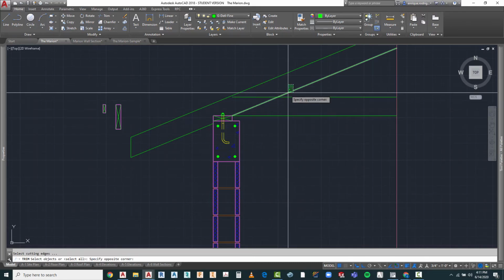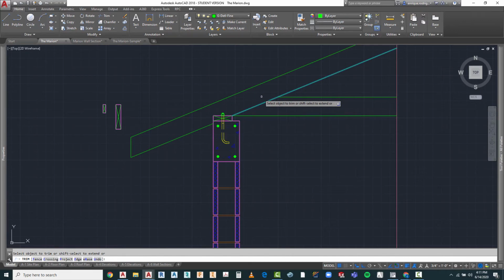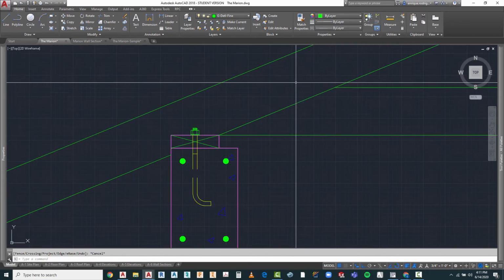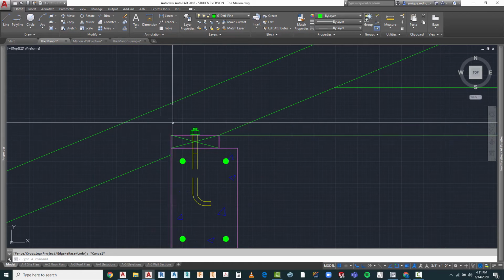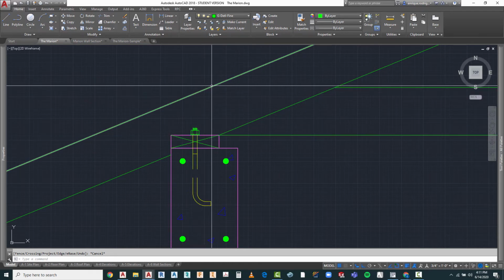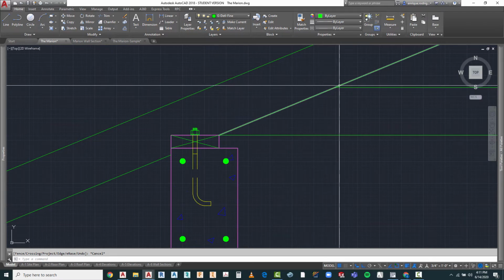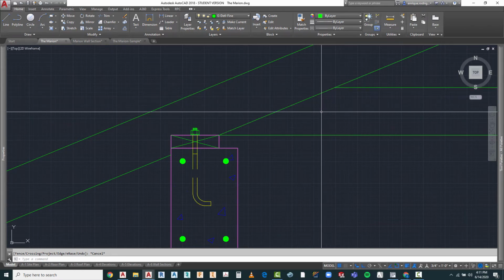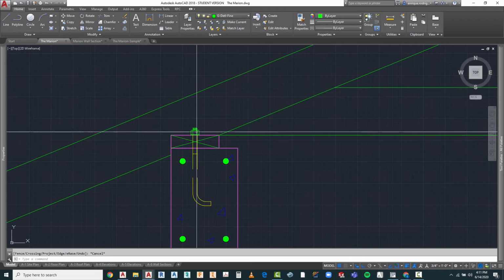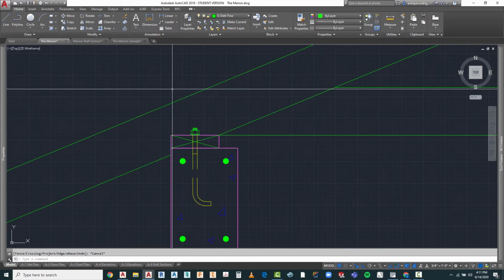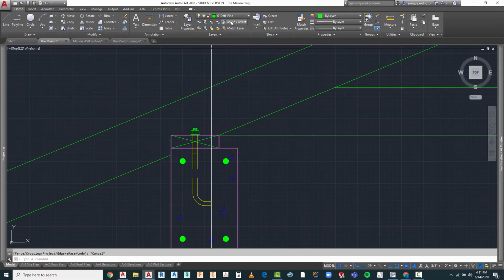What I'm going to do is trim this out, because in this case our ceiling joist is going to disappear when it's behind our rafter. So it's going to go here. We're going to do a cut on the end of that ceiling joist this way, and then bring this across to here. And the reason we're doing that is because if this was a straight edge, it would be sticking up through our roof.